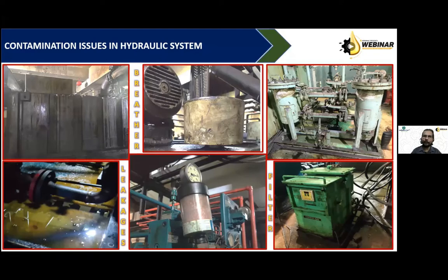But for a 10 kl system where the contamination rate is high, the removal system should be capable enough to take all the contaminant out of the oil. So selection of the purification machine is a different subject, and someday we will talk on this in detail.